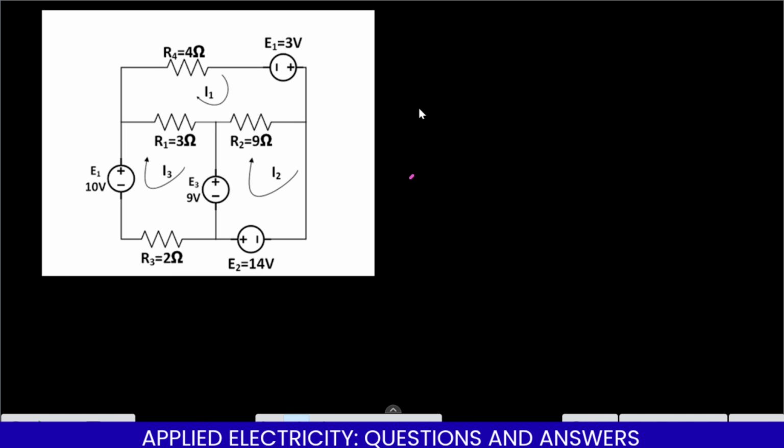And then also we have the short method, and I've explained all this in the series explaining the mesh, the node voltage, and all that. So in this series, I'm going to explain it using the shortcut in solving it, so that we can finish fast. Now the rules go by you summing all the resistances within the loop. So we have 9 in the loop, we have 3 in the loop, and 4 in the loop. If you sum all, you're going to get 16, right?